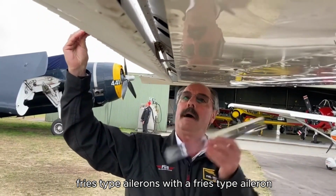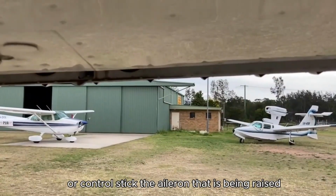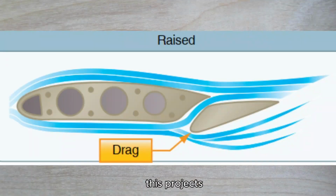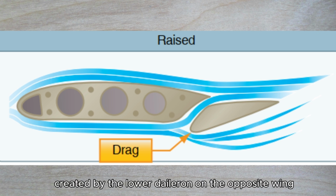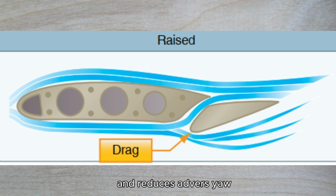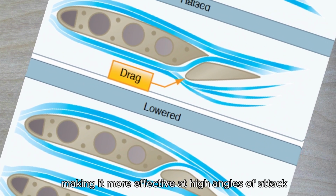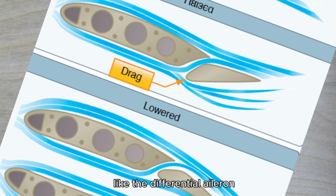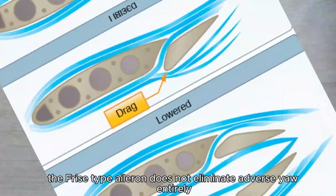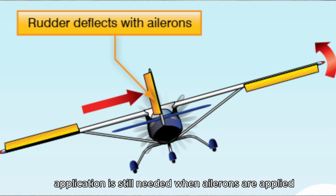Frise-type ailerons. With a Frise-type aileron, when pressure is applied to the control wheel or control stick, the aileron that is being raised pivots on an offset hinge. This projects the leading edge of the aileron into the airflow and creates drag. It helps equalize the drag created by the lowered aileron on the opposite wing, and reduces adverse yaw. The Frise-type aileron also forms a slot so air flows smoothly over the lowered aileron, making it more effective at high angles of attack. Frise-type ailerons may also be designed to function differentially. Like the differential aileron, the Frise-type aileron does not eliminate adverse yaw entirely. Coordinated rudder application is still needed when ailerons are applied.